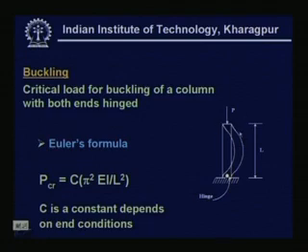The column structure will again regain its original position. So, this is some sort of stability which comes into the picture whenever we design a machine element having a slender column like that. One example you will be learning later could be a screw for a screw jack, which requires to be designed for a buckling load. This is just one example I am trying to give you.